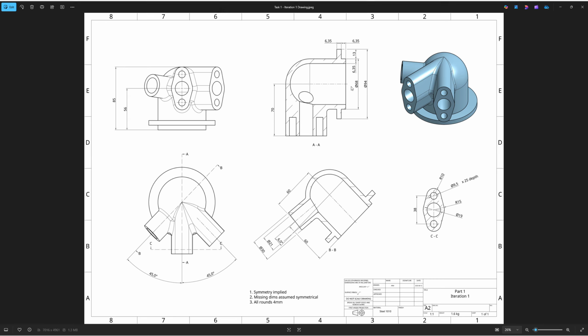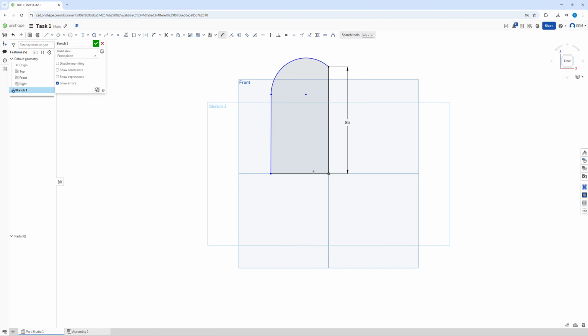85 up there. In terms of its width, so it's going to be 68, sorry, in terms of its diameter, and then we can do these other bits in a second. So 68 diameter, so click on D for the dimension tool from here to here. That has got an angle which is not good. It suggests that and that are not parallel, though they should be, so we make those two parallel. And if we go back into our dimension tool with D, we can just go on from here, that's fine.